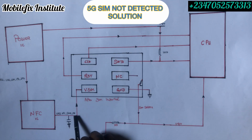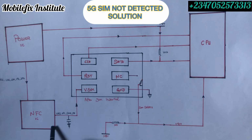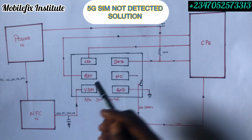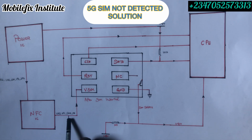So when you test this 1.8 volt, ensure that you get this voltage. If you don't have this voltage, you troubleshoot this line, make sure that this NFC IC, you reball it or you replace it, or you check if there's an open circuit. Ensure that this 1.8 voltage will enter this pin. Okay, after you've inserted your SIM card. So when you insert your SIM card, you won't be able to test on this pin. You'll find this capacitor and test this capacitor. Now I'm done with this pin.